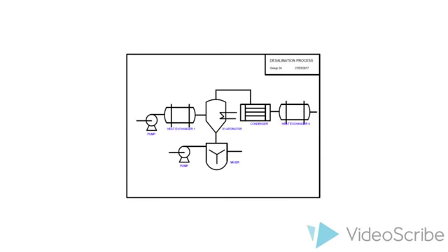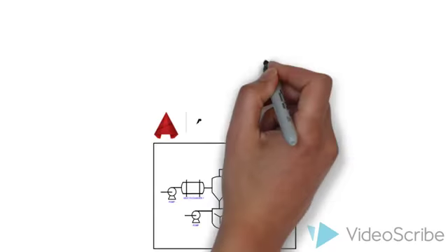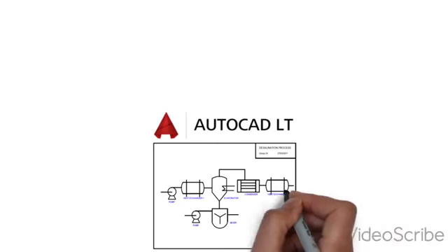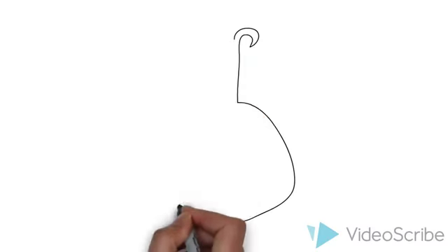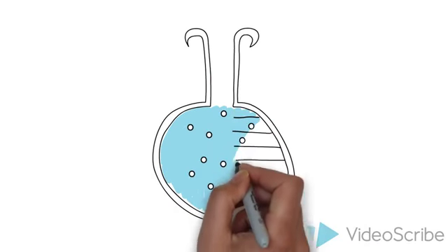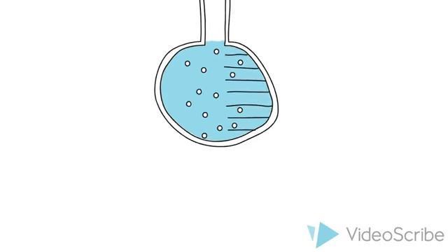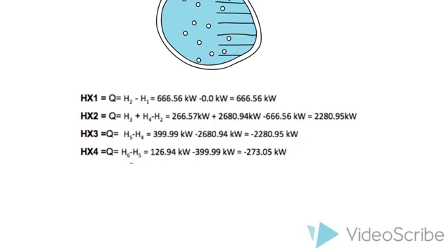The design stage for any process involves developing schematic representations to show the basic components and layout in a way that is easy to understand and visualize. Once we had decided upon which components were needed, we used computer-aided design software, AutoCAD, to make a process flow diagram. Next, we calculated the heat duties for the heat exchangers, heater, vaporizer, condenser, and cooler, using a combination of mass and energy balances and information about the composition of the seawater as well as the temperature.